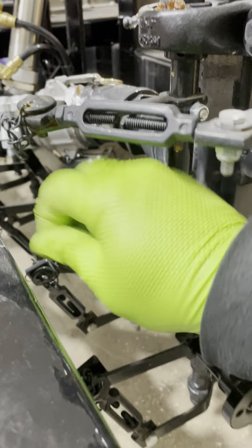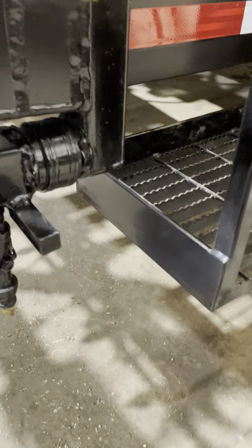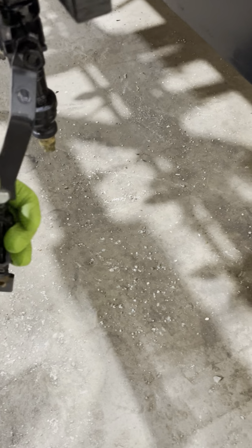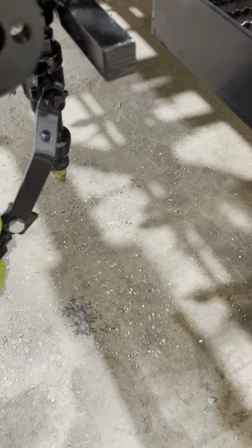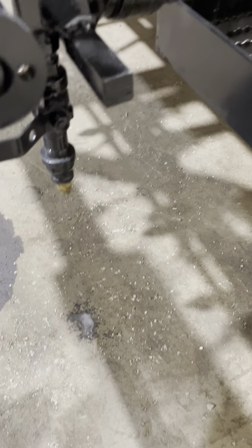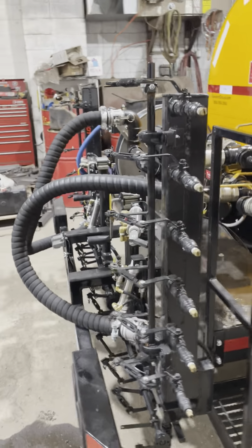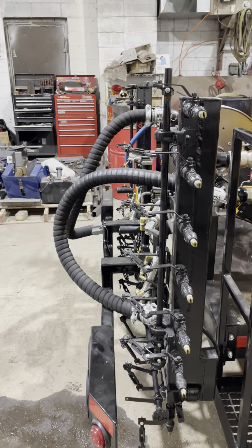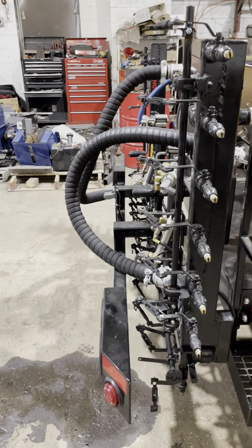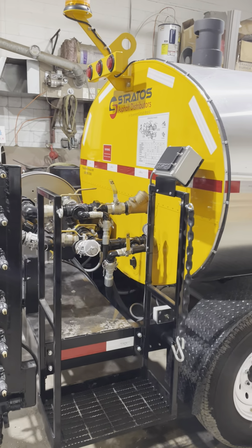We'll pull the pin, pull it out, and then we open the valve. We give it one little shot. It lets the solvent come out, any residual material in there. We close it off, and we do that one valve at a time. I recommend doing every valve so that they don't get gummed up on you, and you're guaranteed that this thing is ready to operate the next time you start it up. Solvent recirculation and spray bar clean out.